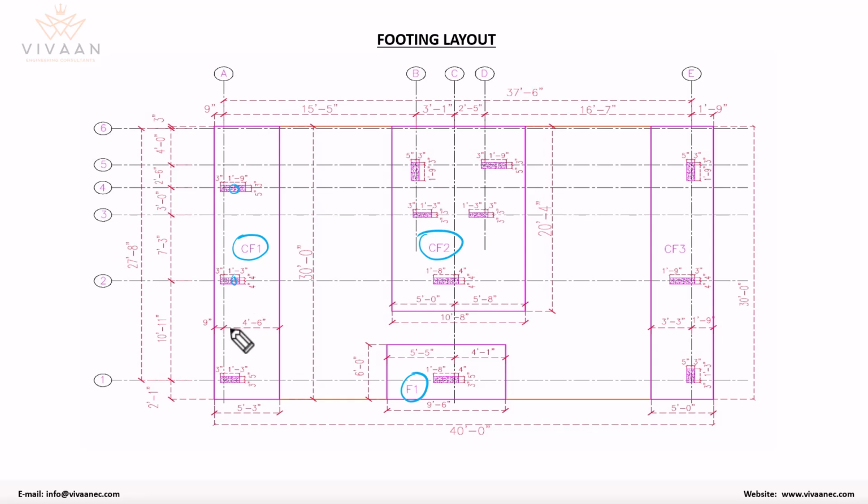So basically we prefer, even in the design drawings, we mention 550D grade of steel. Okay, so if you are going to construct your own building and if the designer gives 550D grade of steel, please let the shop owner know. If you don't ask them specifically for 550D, he's not going to use it. Even if you give it to a contractor, if you don't mention 550D, although he knows, he won't take it up because there is a slight variation in the price of the steel for 550 and 550D on any company steel. Okay. Now let me go on to the next set of drawings.